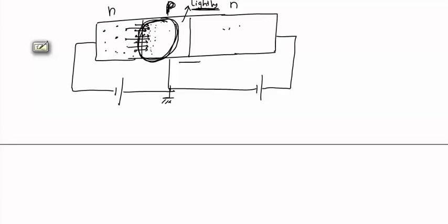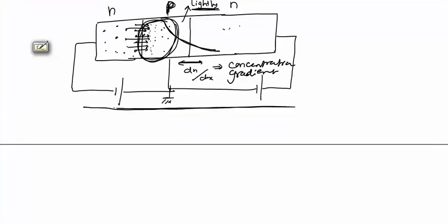So we can say that between these two regions there is change in concentration with respect to change in distance, means concentration gradient is created. If concentration gradient is created, these charge carriers will diffuse from higher concentration to lower concentration, means these charge carriers will reach to the collector. This is the basic operation of BJT, and now we will discuss about the doping and areas of the region of three layers.